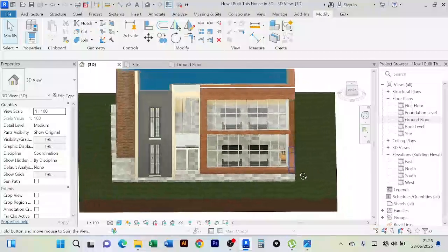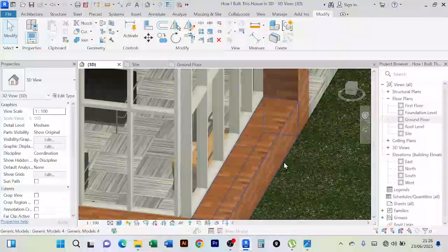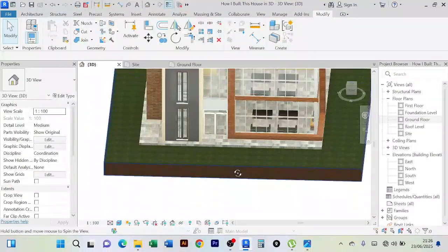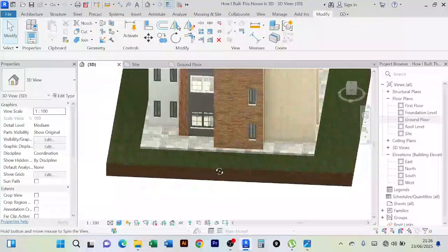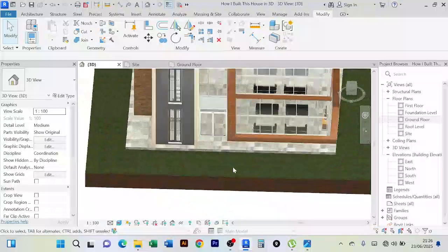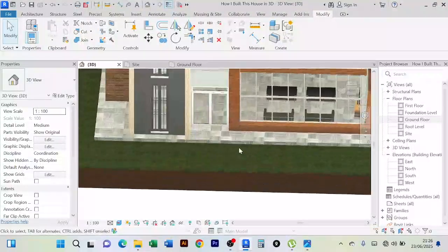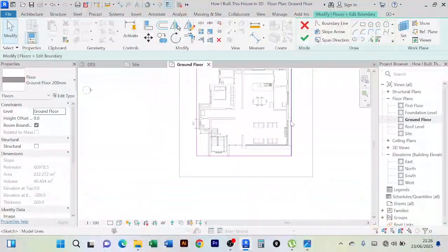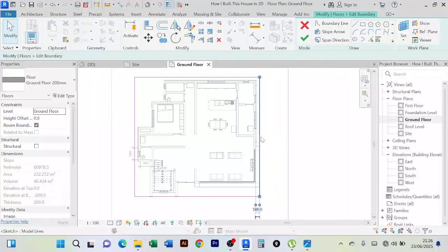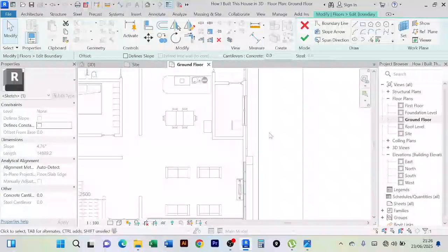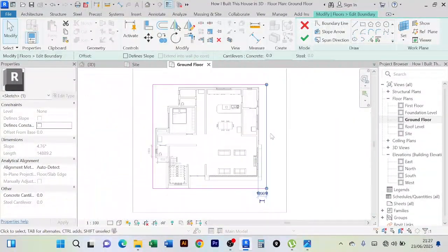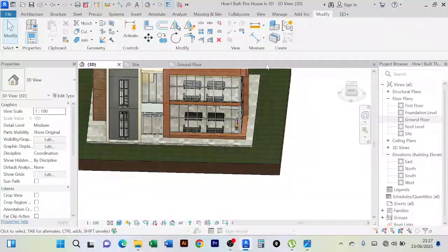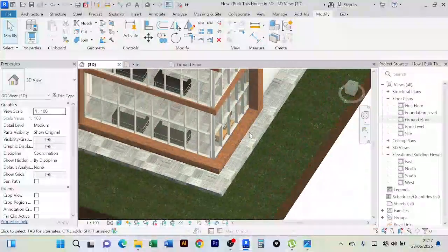However, this side was not extended enough. It doesn't have any veranda at all, but we need to create veranda, I think, everywhere. So we can do that again by just clicking on this. You come to edit boundary, you go to ground. This side has to extend a little bit outside. I'll just now extend it manually like that. Then I'll click OK. Then this time you can see we have now veranda for someone to pass around.